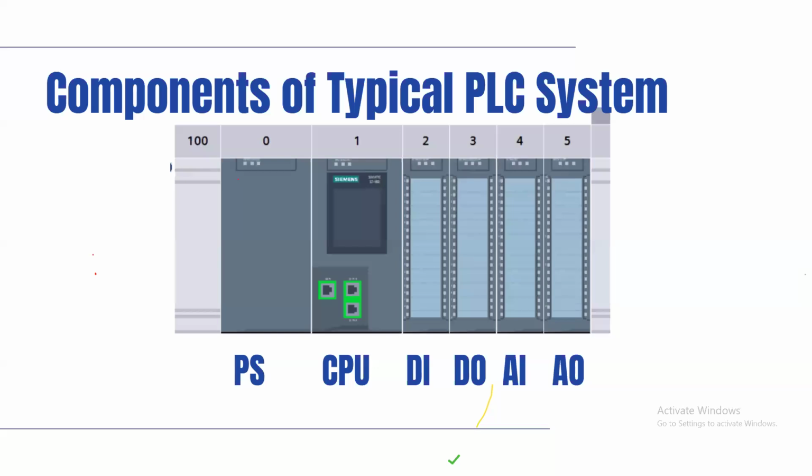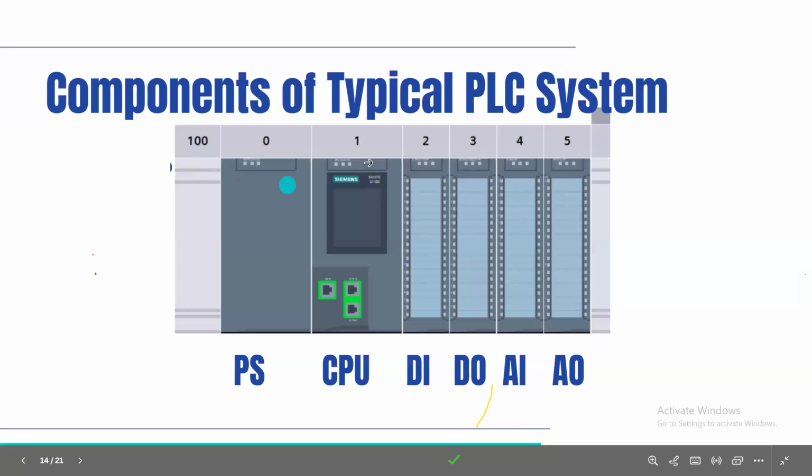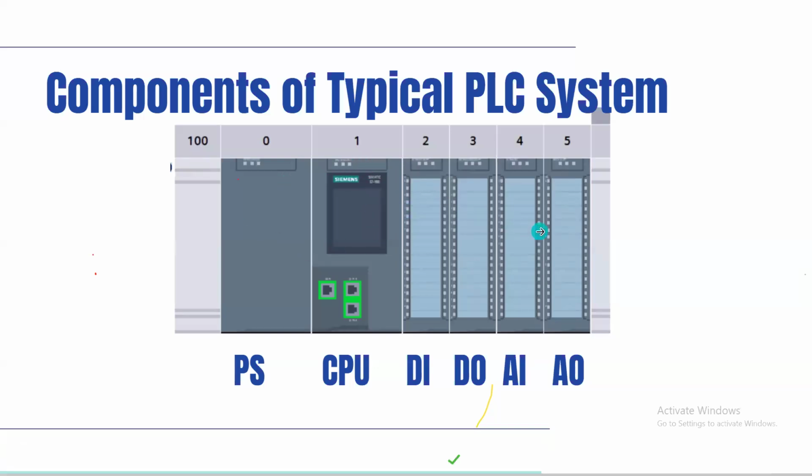One thing I want you all to notice is that you can pick apart the different components of this system; they are clearly visible. This is an example of what we call a modular PLC. Just think of it as your desktop in the office. You have a monitor, your CPU, your mouse, your keyboard, all separate. If your monitor goes bad, you don't need to change the entire system.